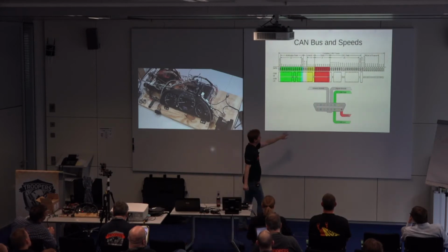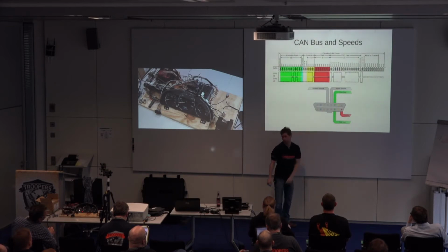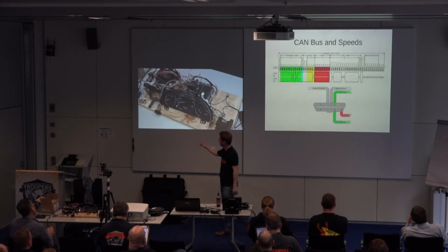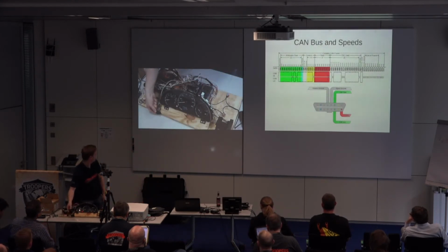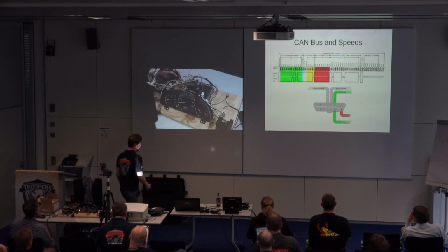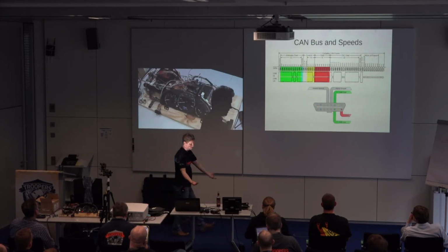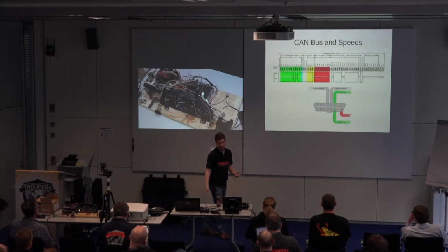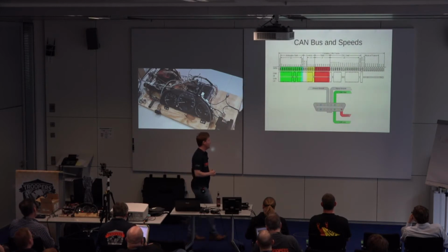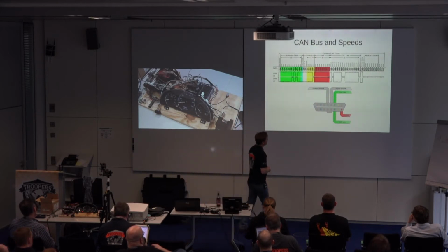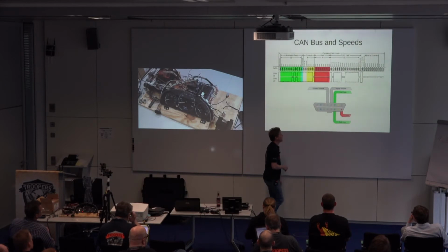So this is your DLC connector. It is also pulled out on this guy right here. So this guy here is typically under your steering column. So you have your steering column, it's either on the right or left side. Sometimes it's somewhere else, but that's where it's supposed to be. If you have any kind of environmental check agency, that's what they typically plug into. And the two pins that are used are 6 and 14, and that is your CAN high and CAN low pins.